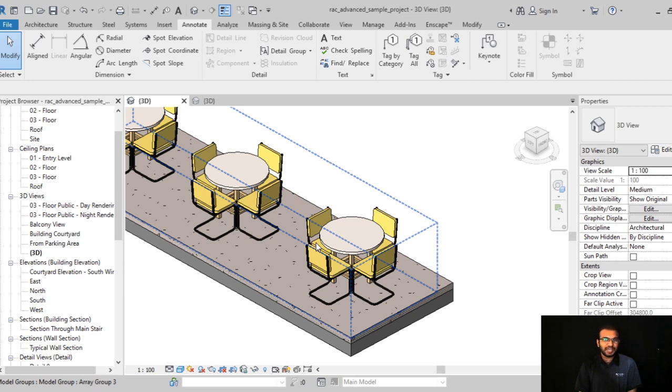That is why I want to introduce a small term to you: LOD. Has anybody here heard of LOD, which is one of the major points we need to understand when working with BIM? LOD means level of detail. In Revit's language it is level of detail, but in terms of BIM you can define LOD as level of development or level of definition.